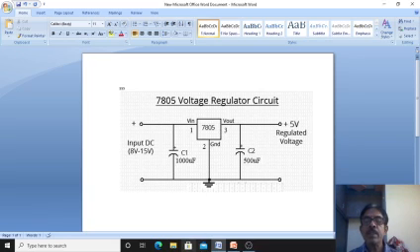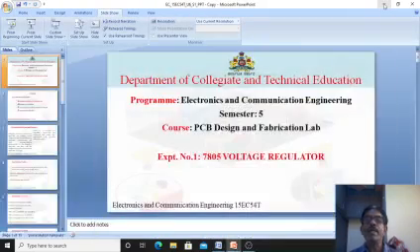And in the PCB lab using KiCad software, I also require another power component. It is called the ground component, and for each power component I require a power flag. So these are the components I require. Now I will show you how to begin the experiment.